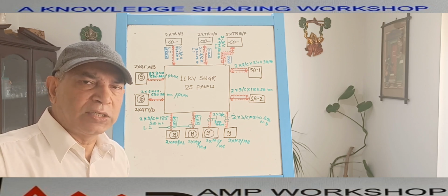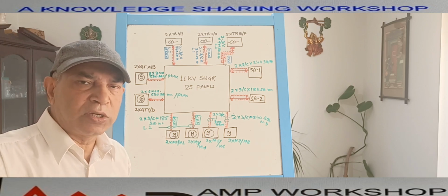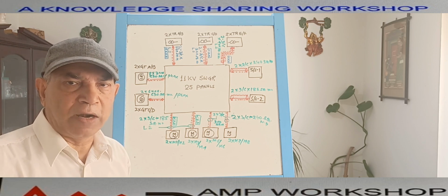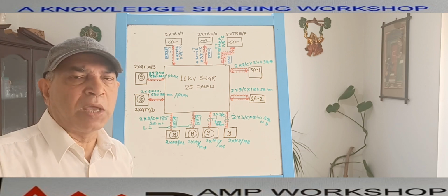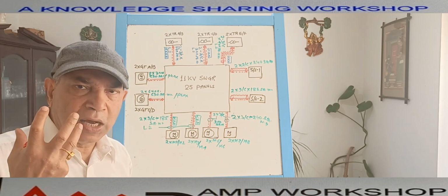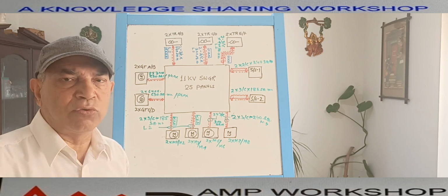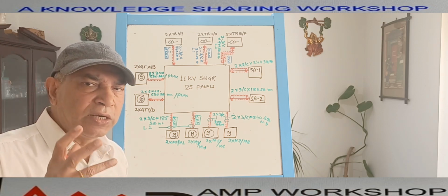So the switchgear, this cable either comes from the top or from the bottom. Each panel has a bottom gland plate, through which the cables are coming. So what size of cable gland is required, what hole size on the gland plate is required, what gland is required to take the cable through the gland plate, all these things we can decide from